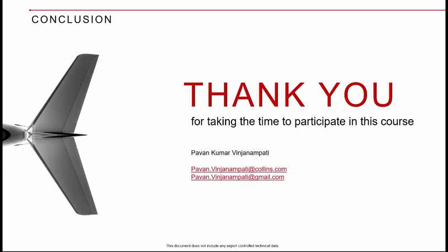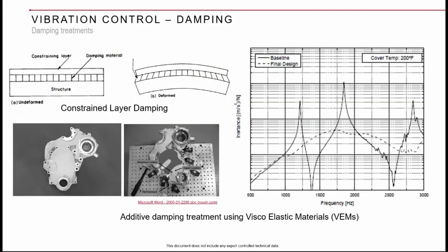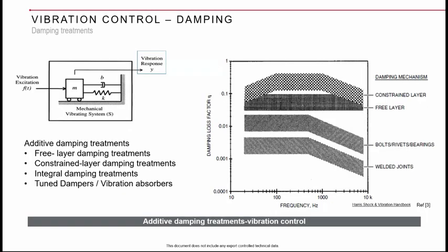We have to take displacement frequency plot or velocity frequency plot or acceleration frequency plot? Yeah, that is a nice question. It depends, but you can take acceleration frequency plot most of the times, because at higher frequencies your displacement may not be so great to appreciate. So that is the reason most of the times we will take acceleration FRFs, accelerance.